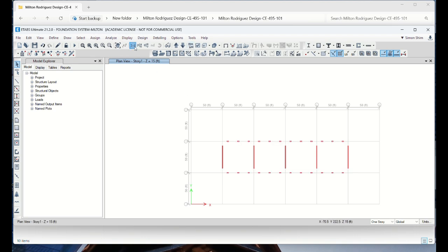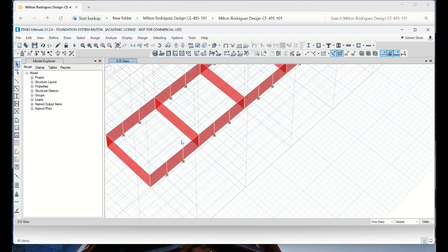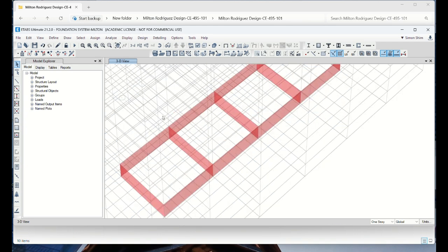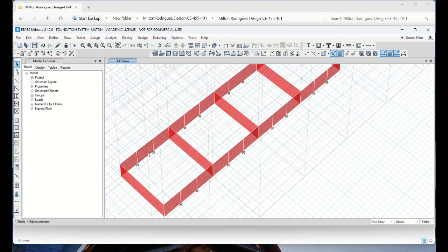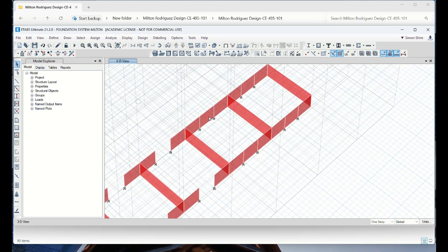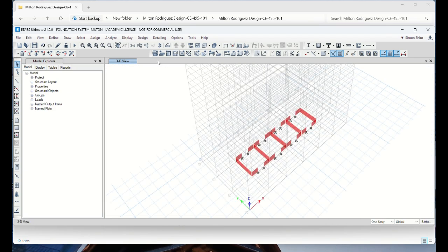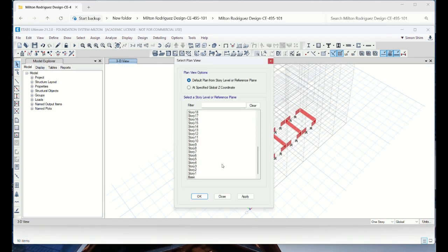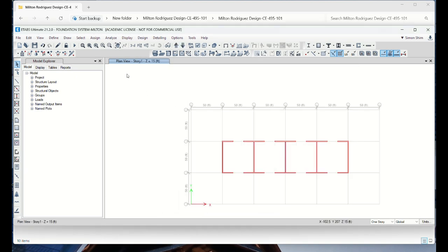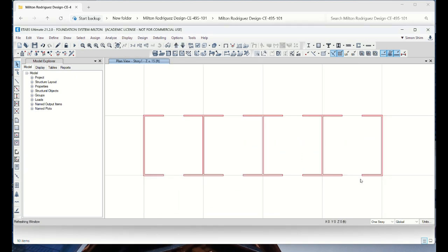All right, so this is the wall profile we're going to use. What we're going to do is delete the middle, so that we assume this is an elevator hole, right? And then going back to plan, we're going to draw the link beam to tie this.